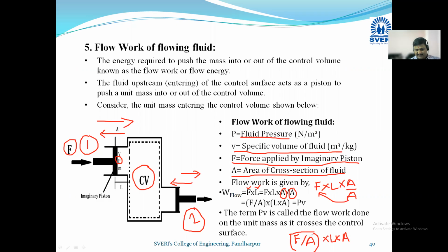Now force divided by area means what? Pressure. Stress. Okay, stress generated, or the pressure. Can we see? Yeah. So it is the stress or it is the pressure in this particular case, multiplied by length into area is nothing but what? Volume. So the flow work is nothing but the pressure into volume